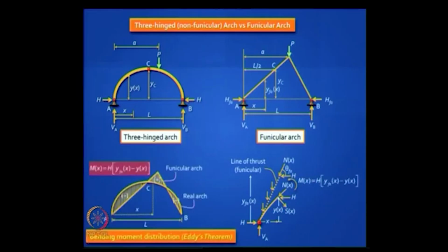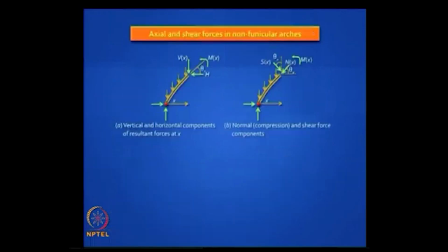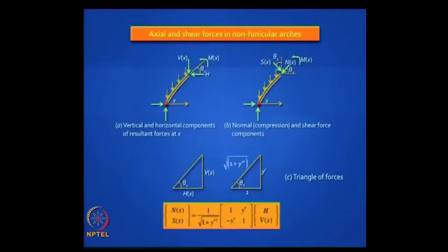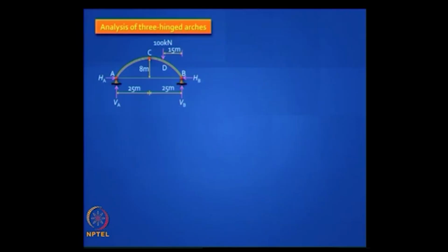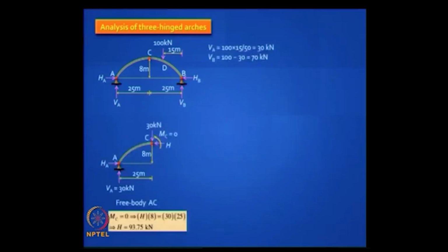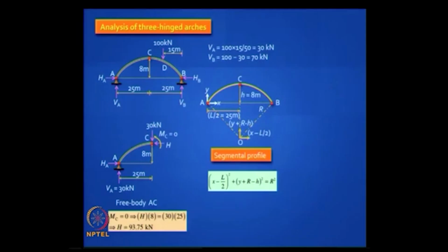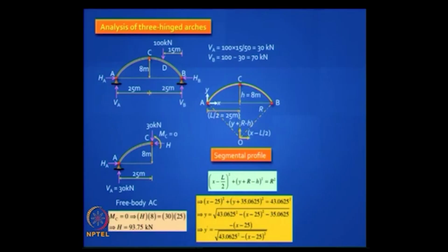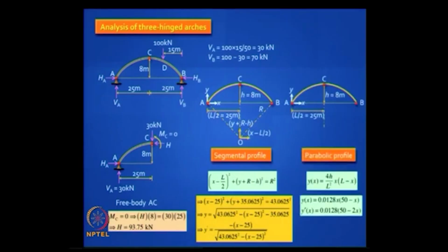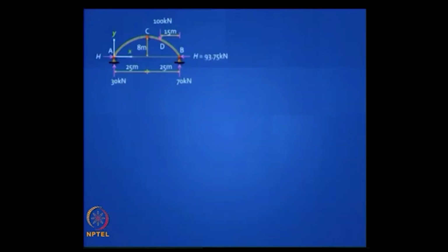The other thing you need to know is you will also get shear forces and axial forces, and you can resolve the vertical force and the horizontal thrust into axial and shear forces using the geometry of the arch. You have studied all this, and these are simple examples that can be solved. These types of arches are often either segmental, which means part of a circle, for which you can derive the equations, or they are parabolic. We do not have time right now to solve a full example, but it is pretty easy to solve.